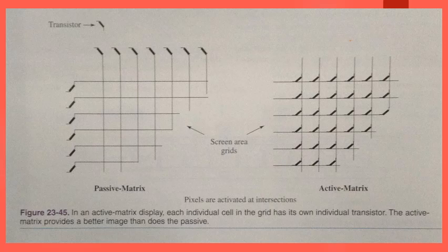The grid is divided into two major circuits, columns and rows. Transistors running along the top and side of the display unit head the columns and rows. A ground is applied to a row and a charge applied to a column, which activates a pixel area.